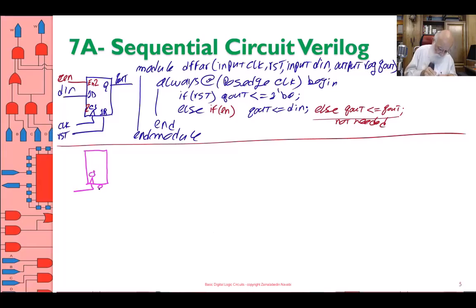C1 again. Let's do synchronous active low reset, and therefore I have one R here, and then this is Q, this is Q out, and then 1D here. And so let's write this down. Module D flip-flop asynchronous low reset, just making up names.